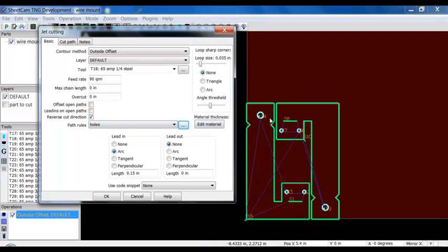By slowing your holes down, you get far more consistent holes. So even if I have worn consumables and I'm cutting thicker plate, I can know that I'm going to get a higher quality hole provided I slow it down. So, very nice feature. I highly recommend you use it.